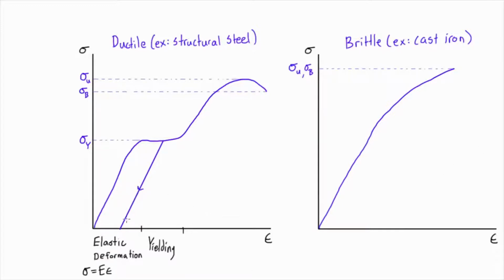the stress strain profile actually goes down like this, and it won't return to 0 strain because we've actually reached the first part of our plastic deformation now, and some of these strains will now be permanent. So if we reduce the load down to 0, we'll get stuck with some of these strains and this plastic deformation, and then when we reload it again, now it's going to follow this pattern here on the stress strain curve when we're applying that incremental